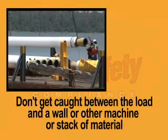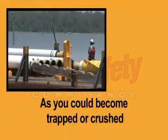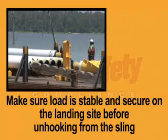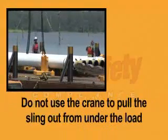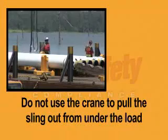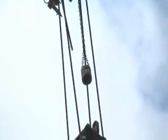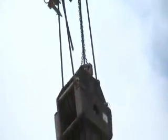Don't get caught between the load and a wall or other machine or stack of material, as you could become trapped or crushed. Make sure load is stable and secure on the landing site before unhooking from the sling. Do not use the crane to pull the sling out from under the load. Once crane rigging is removed, return crane hook to upper limit switch.